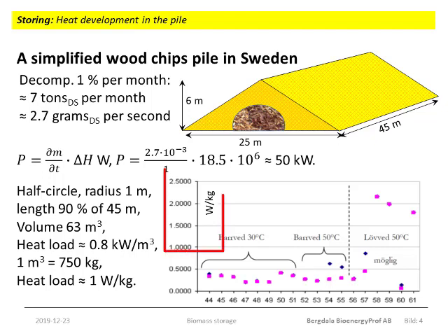The vertical axis is the heat developed in watts per kilo. The horizontal scale is the sample number. The groups are, to the left, bark and conifer wood chips, kept at 30 degrees for a week and at a moisture content about 40%.